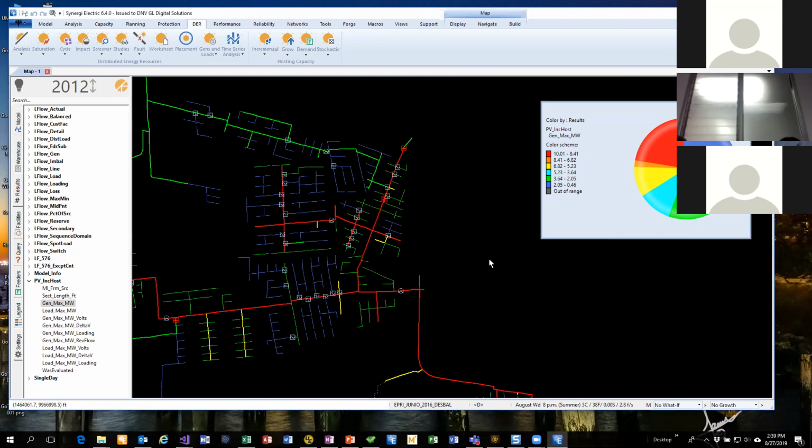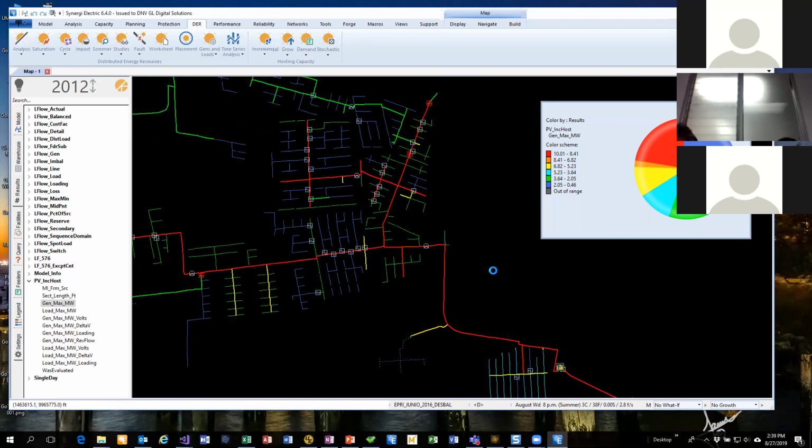And then the last one is reverse power flow limits, and those are arbitrary limits that utilities will specify. Some utilities have a reverse power flow limit of infinity. They have none at all. And others will have theirs set to zero. They will not allow any reverse power flow. So you can specify what that is. So we look at those 5 things and then use that to generate the heat map for the distribution system.